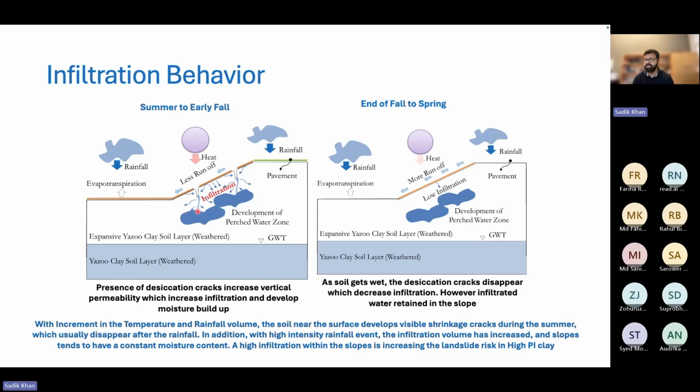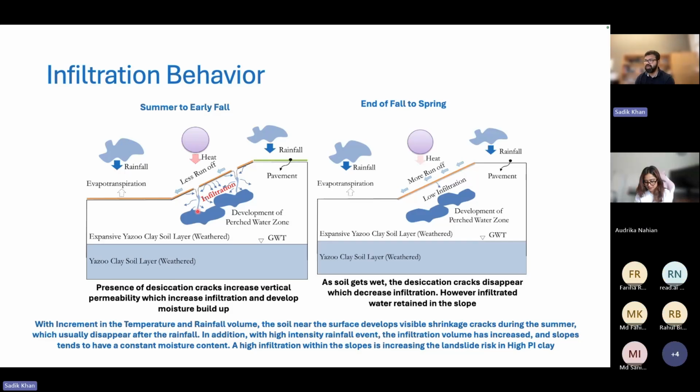There are many different solutions for that. Reinforcement is one of them, like piles. We can use piles, we can use soil nails, we can use recycled plastic pins, and we can also use other measures like horizontal drainage and so on. In reality, many different techniques have already been used, such as geogrid, and geostabilization is another one. And all of them have been proven very well.